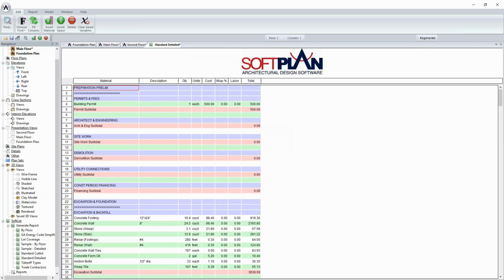While it's running this through, we didn't get an error prompt, but it's possible that during the drawing process of your project, you may wind up, let's say, spanning your joist 20 feet. At that stage, you may get a warning prompt that simply says we couldn't find a cost associated with this length of lumber. At that stage, you can either accept it or cancel it and go make the changes to your drawing.